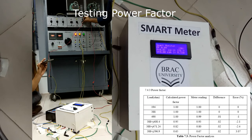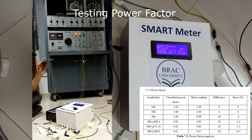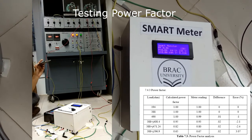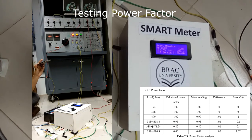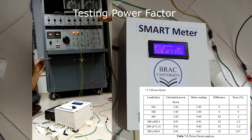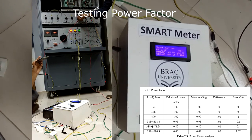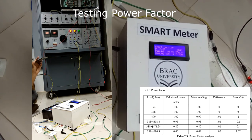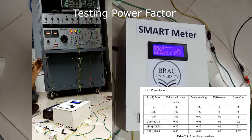Here you can see a different setup to test our power factor. We have added inductive load instead of the bulb box. Testing power factor is a lengthy process, as we get a stable value in 3 to 5 seconds. So we have included this chart to make it more clear to you. You can see when we are using resistive load, the error is almost 0%, and when we are using inductive load, it goes up to -2 to 3% error.